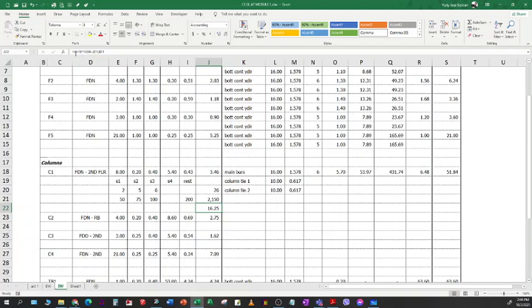Okay? So let's add something to make the formula more accurate, which is to round up to the nearest whole number. So round up, 0. So it became 17 instead of 16 point something. So 17 ties. And then it is a good habit to always add 1 just for allowance purposes. So plus 1. So that will be 18 ties.